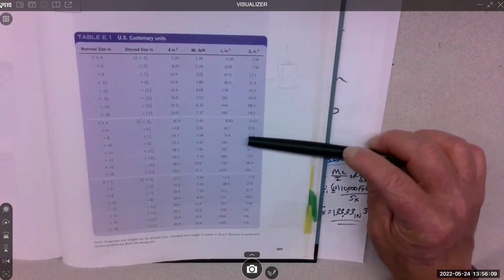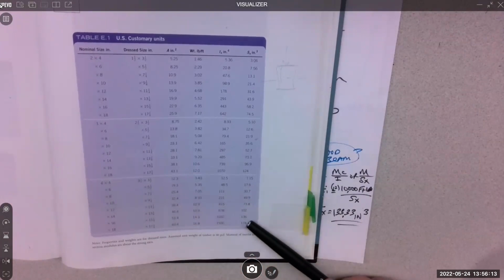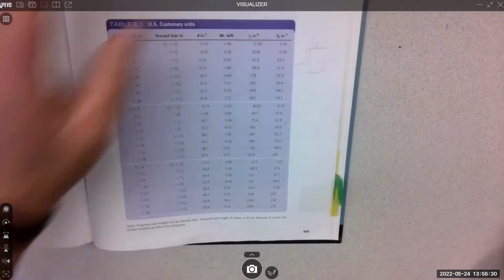So looking down, here we are at the 4x material. We're still not there, so see if we get larger wood pieces. 4x 133, is there one in there? Oh yeah, there is, you're right. So 133 is the minimum. We can go over it, we can't go under it.